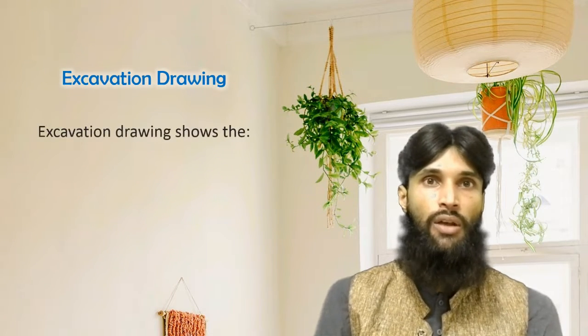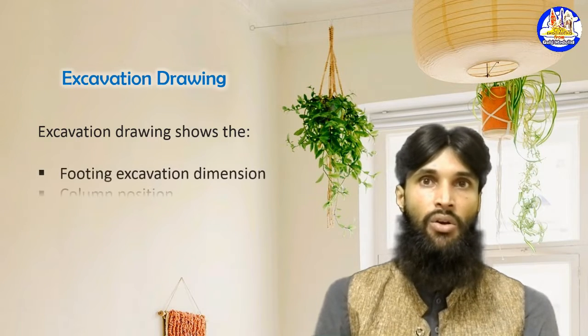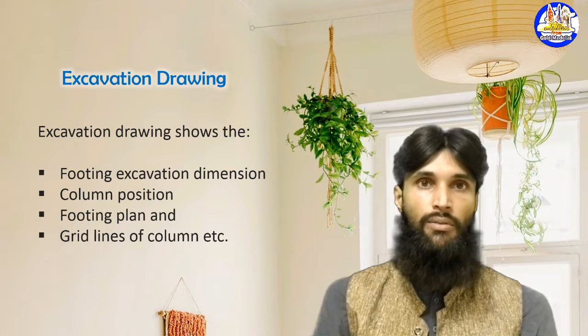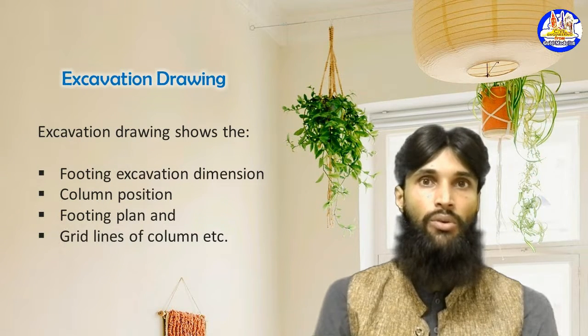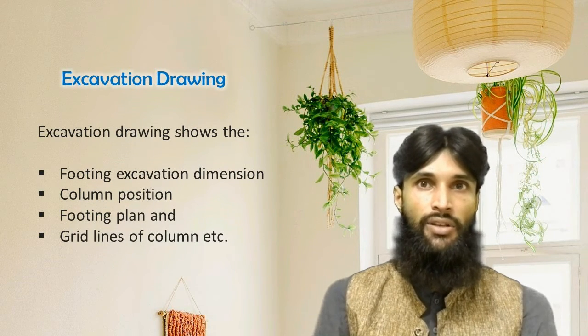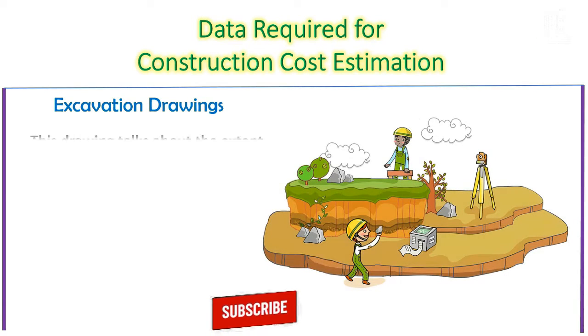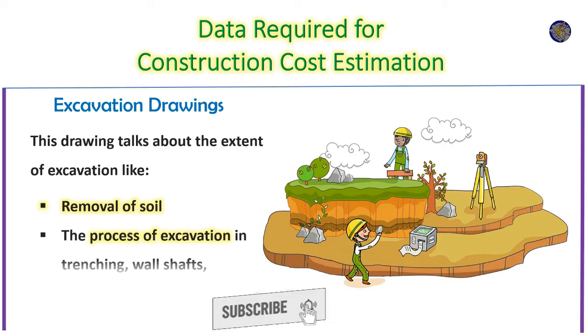Excavation drawing shows the footing excavation dimension, column position, footing planes and grid lines of column. This drawing talks about the extent of excavation, that is the removal of soil and the process of excavation like trenching, wall shaft, tunneling and others. Column layout.